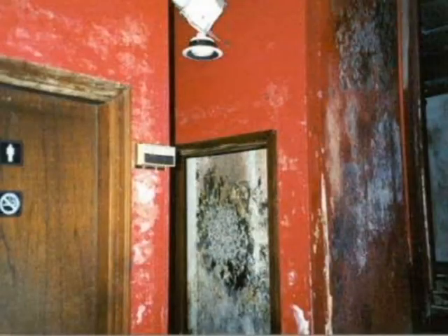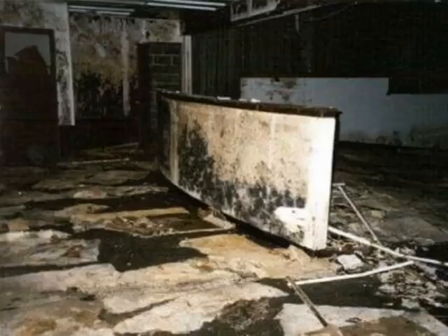Mold is another hazard you can find in buildings. There are thousands of species of mold. Mold can cause several reactions, including allergies, eye irritation, or respiratory problems. If you encounter moldy odors or visible mold, or know you'll be entering damp, humid areas, you should be using proper respiratory protection. A HEPA filter and organic vapor cartridge should be adequate protection against mold and odors.